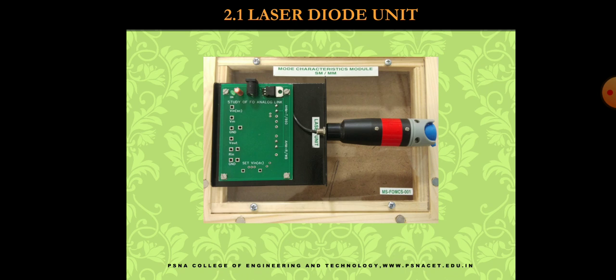The ferrule is the precision cylindrical ceramic part at the tip of the cable. Optical power coupled into the fiber may be adjusted by positioning the ferrule suitably, back or forth. Please note that the cable connector fits into the notch provided on the laser diode unit.